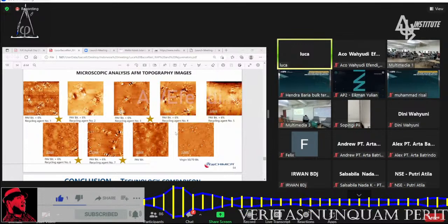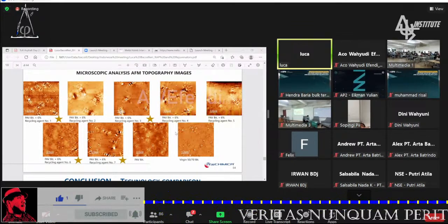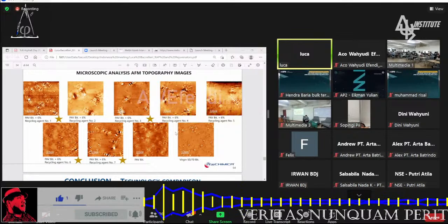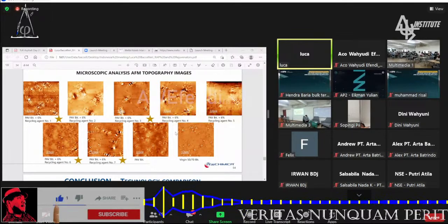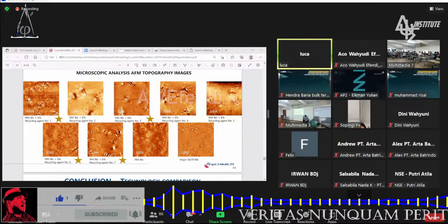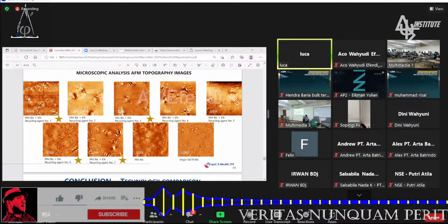Well, the point is this one. As we said, even to our other clients, this is not an aromatic oil. It means aromatic works in that way. So they change the SARA parameters. In this case, we saw what happens when we change the asphaltene, because the stiffness and the main problems are connected to the asphaltene. So with a structure with bigger asphaltene, let's say, the stiffness of the material can be higher.